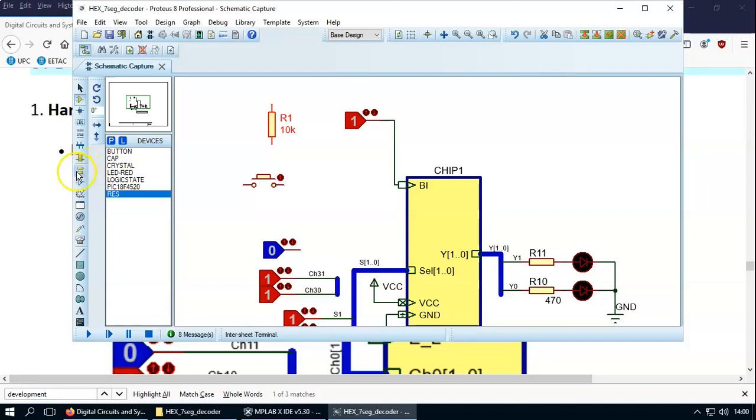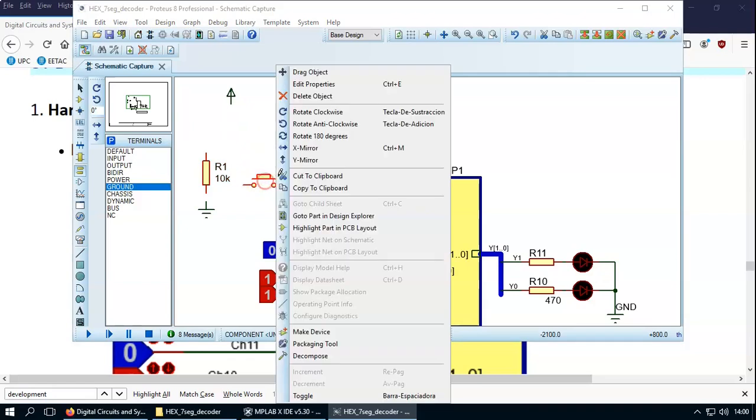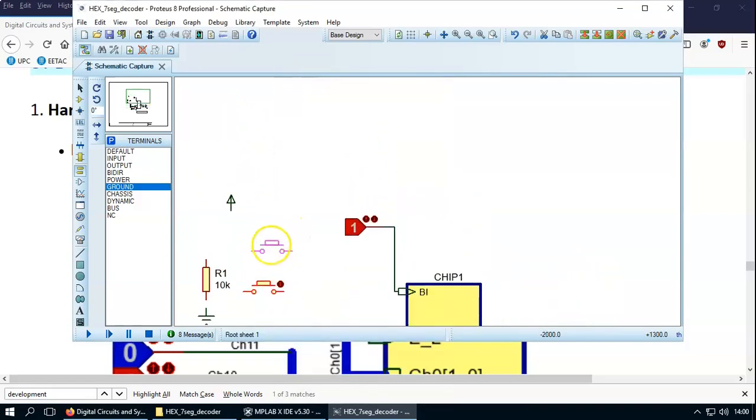And now it's your turn to add connections to the power, which is going to be understood by default as a 1, you see, and then to the ground. That is what you do here. Now you have an, well, wait a minute, because I'm thinking now in an active high button. So you see, I will place the resistor on the ground side, and the button, I have to drag it. It's that idea.